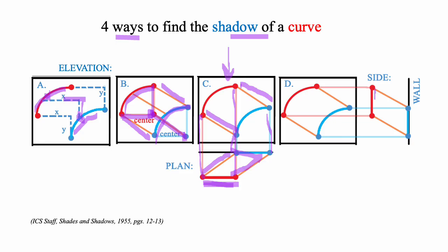If we're using the side view, it looks like a vertical line. Send light rays down to the wall to find the shadow on the wall. Transfer that information over to the front view, and where it intersects the light are 2 points on the shadow.